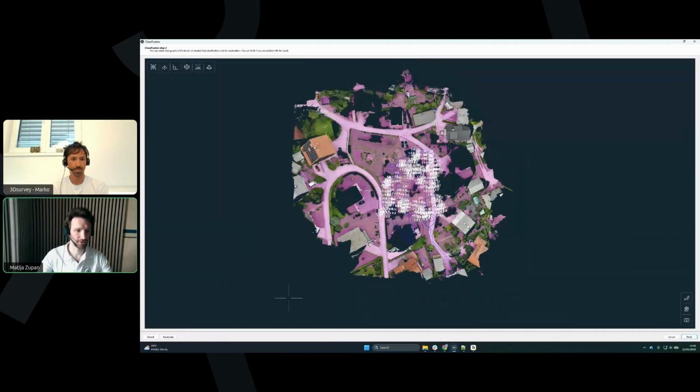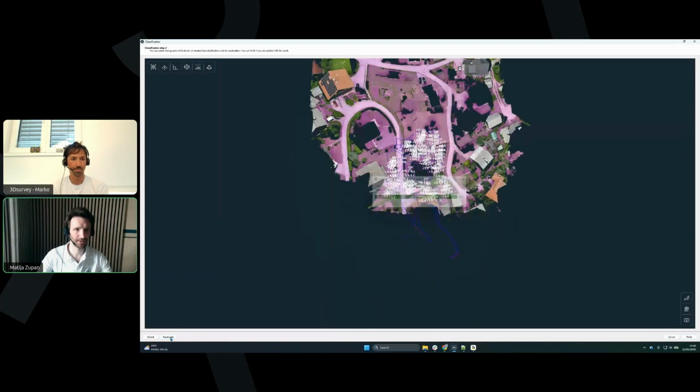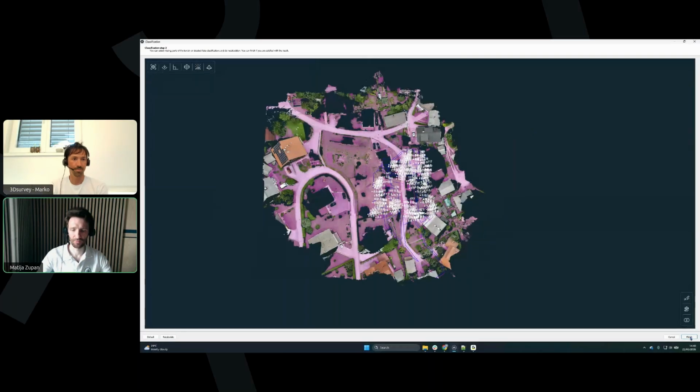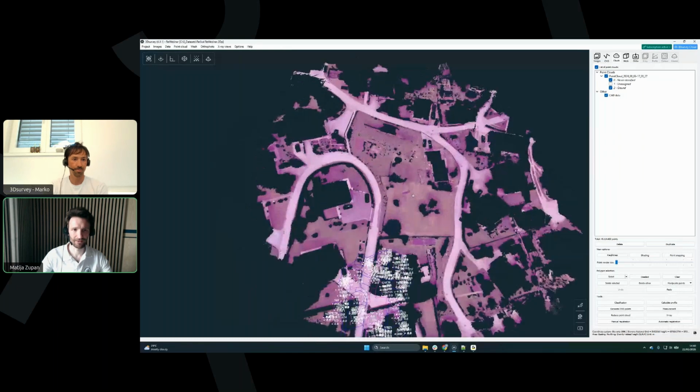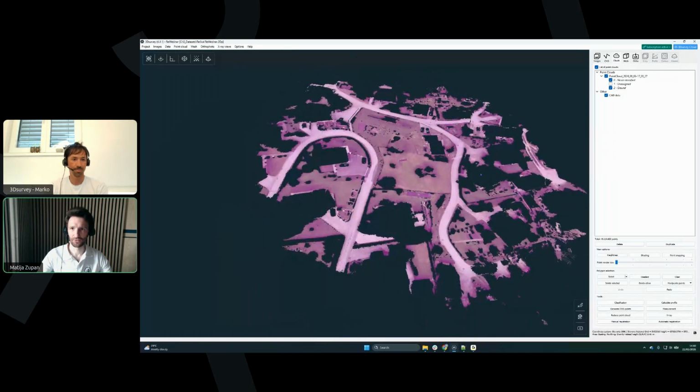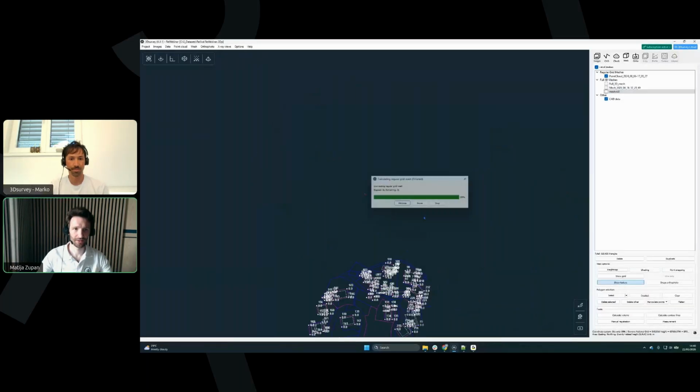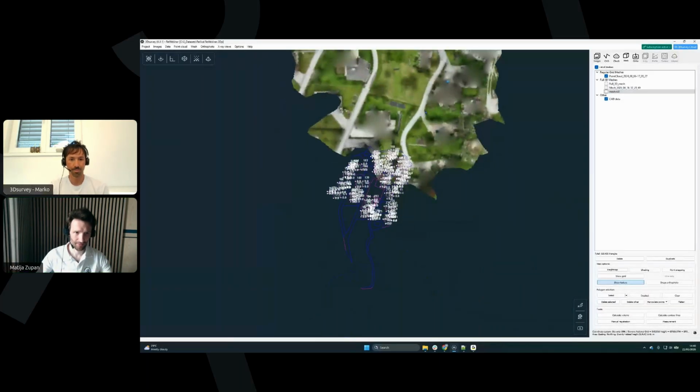It's looking pretty good. If it's not perfect, click recalculate. One more time. Okay, now should be good. Finish. And yes, the roofs are gone, and all I have is this ground. Now, mesh, calculate new DSM. Half a meter is good. Optimized hole filling. Perfect. And this is my surface.